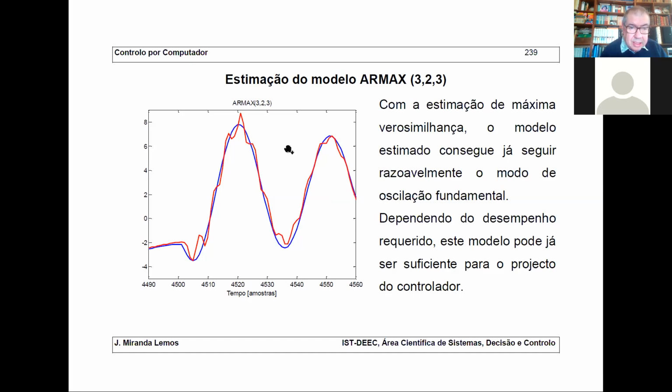So it's wise to have simple controllers, and if you can start from a simple model, then you get a simple controller, and this is advantageous for the design, because you will gain nothing much with respect to the model which replicates the high frequency gain.